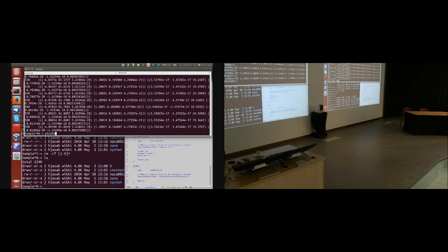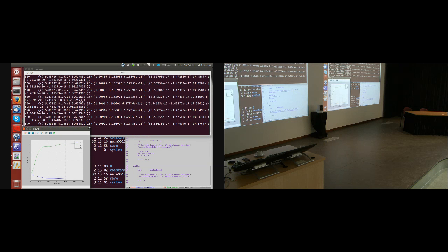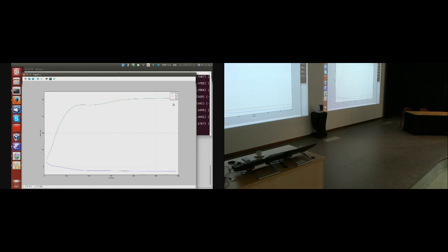With Foam Extend, I have a little tool called plot forces, which will create an XY graph of your forces by removing all these brackets. Okay? This is usually a good measure of convergence. So around here, say 400 iterations, my force is pretty well stabilized, and I can declare that my simulation has converged. Also, this is 2D, so the Z force will be 0. Okay, shall we do some visualization?